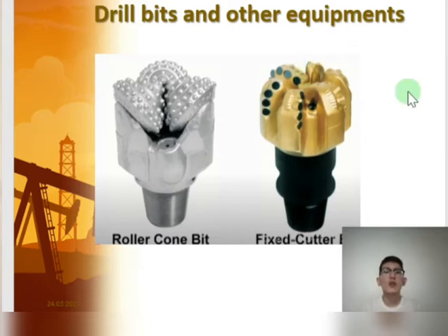When we drill our well, we have to put our casing there. We know that casing is a large diameter steel pipe which is used to line the hole during drilling operations, and it has four types: conductor casing, surface casing, intermediate casing, and production casing. And each casing has its own purpose, like the conductor casing protects the freshwater zone.